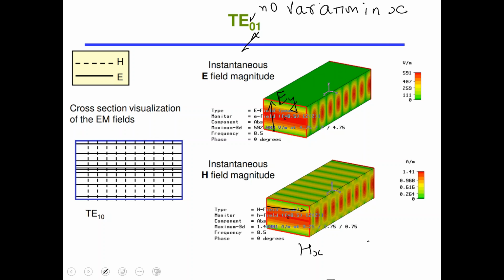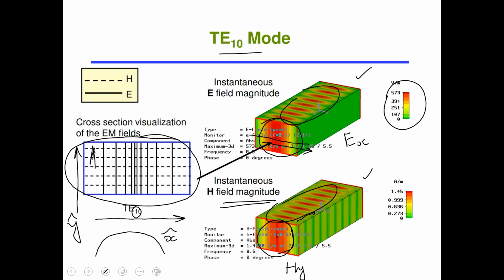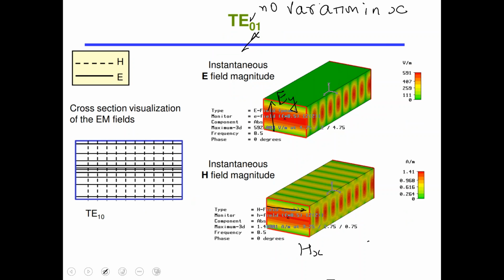Because there is no symmetry in this waveguide, because A is not equal to B in the general case, the propagation constant of this field is going to be different than the propagation constant of the previous field we have over here. The velocity with which these two fields are traveling is going to be different. They are two independent eigen solutions of my Helmholtz wave equation.